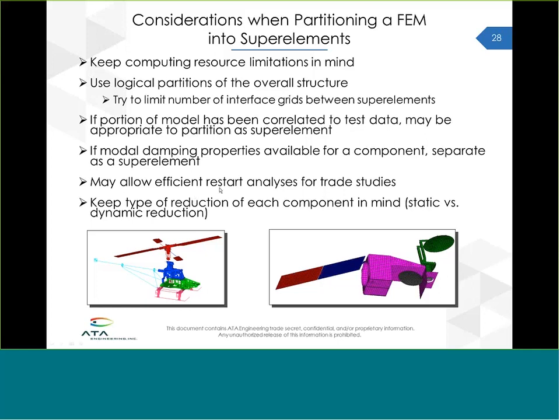Again, if you're going to be doing restarts, keep that in mind. So if all your trade studies are going to be done in one portion of your model, if you try to keep that in the residual or close to the residual, then that can be beneficial to minimize the amount of essentially rework that Nastran has to do. And then, of course, you have to think about whether you're going to be doing static or dynamic reductions for each portion of the model.